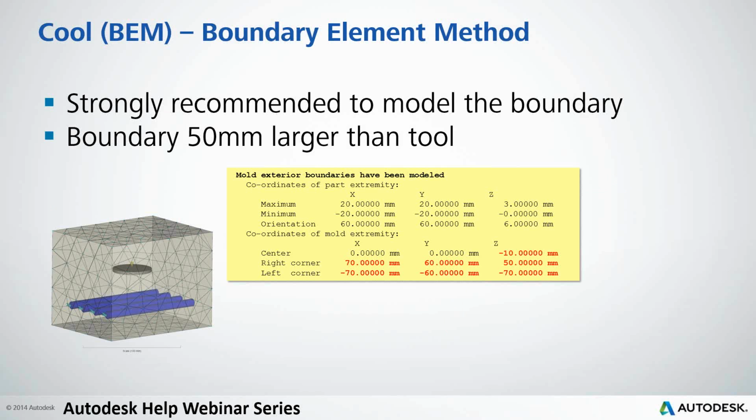Okay, so we are talking about a boundary method, so we need a boundary. So probably you know that you don't need to create a boundary to run such a kind of cool analysis, but that you don't consciously create a boundary does not mean that the boundary is not there. If you don't define the boundary, Moldflow will define it for you. In this case, we strongly recommend to create a boundary because, as we saw, there is radiation energy which gets lost on the surfaces of the tool.